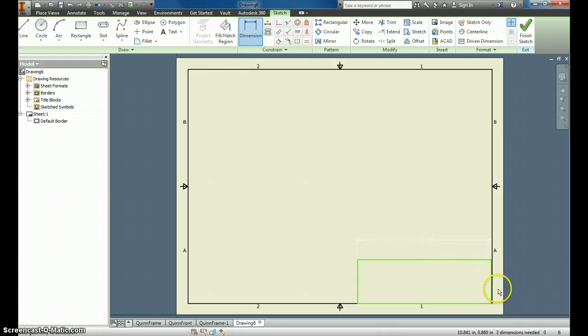If you do it any other way, the line will actually push backwards and get into here and look ugly. So you have to click from here to there to make it 4.5. Now it's hard to see, but that dimension is hiding right there. Now I click Dimension again, and I'm going to come over and dimension this one, and it is supposed to be 1.25. And so you see it shrunk itself down.